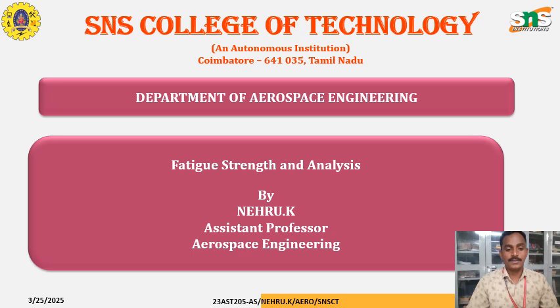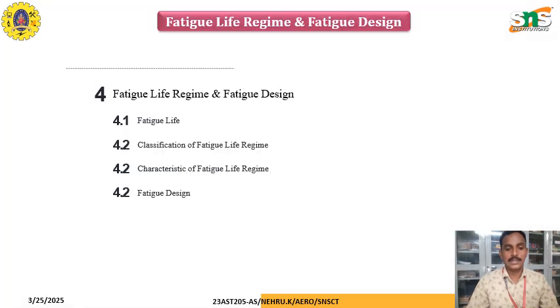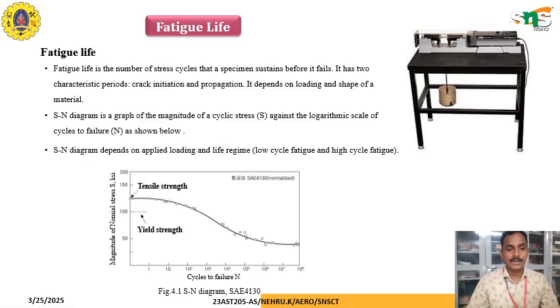So, in continuation of the fatigue strength and analysis, today we are going to see the fatigue life regime and fatigue design. Here we are going to discuss a few topics like fatigue life, calculation of fatigue life regime, characteristics of fatigue life regime, and fatigue design. Fatigue life is the number of stress cycles that a specimen sustains before it fails. It has two characteristic periods: crack initiation and propagation. It depends on loading and the shape of the materials.